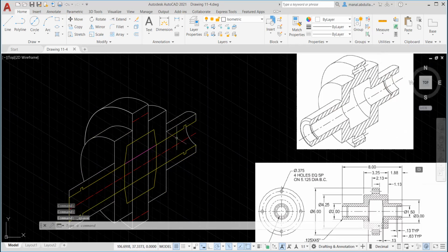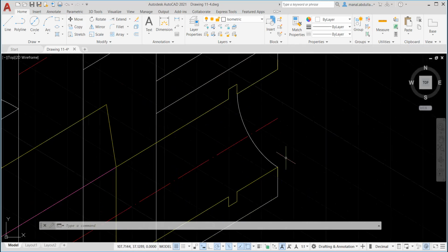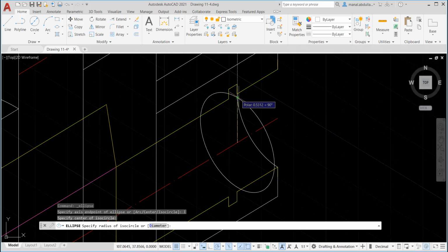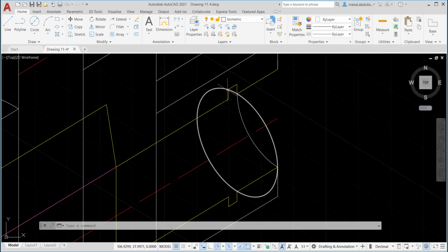To draw the circles inside, we're gonna use the same strategy. Zoom in, axis end, isoplane, specify the center. Here, because we already deleted that, we can just get the center by tracking the point. Okay, and here you go. So this is the circle that we want. Actually, from this circle, I just need the part that's from there and the rest of the arc.